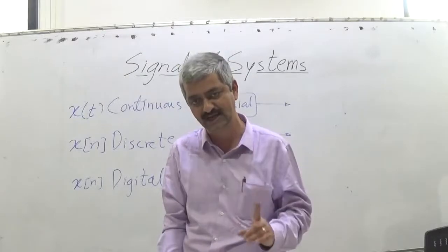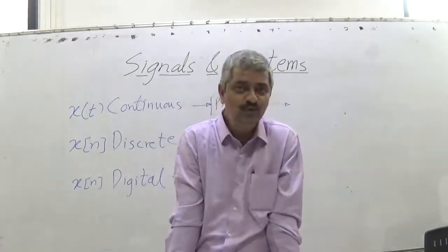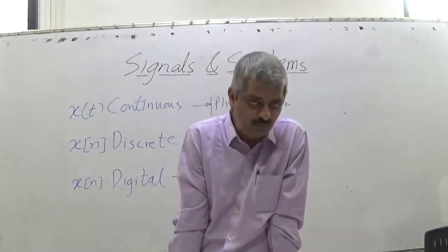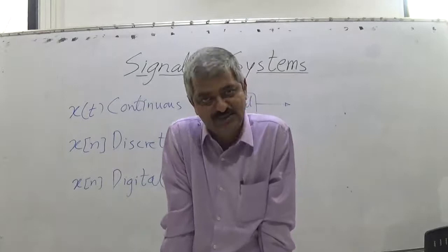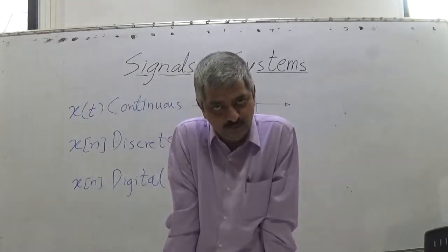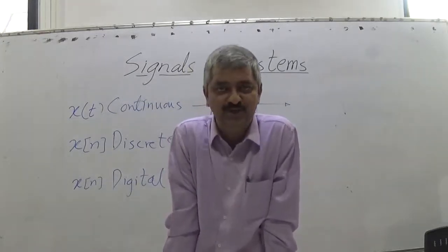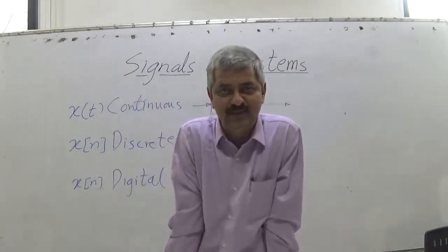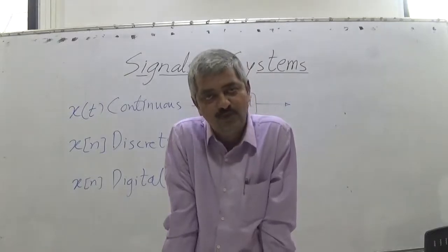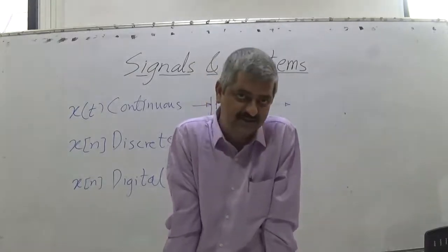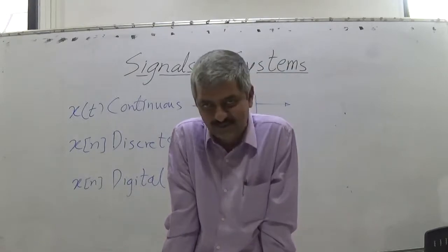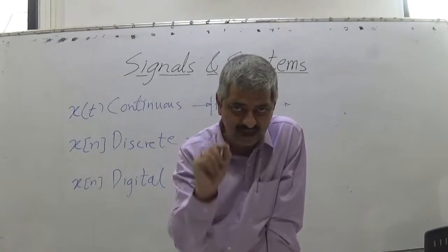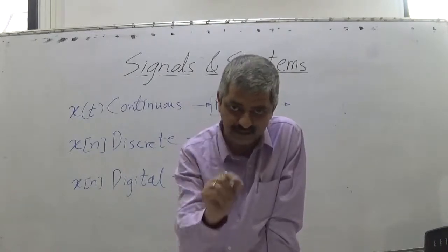So what you have to decide is, when you are having a finite number of digits, you have to define how much resolution you want and how much maximum size you want. If you want lesser resolution, for the same digits you can express a larger size. If you want finer resolution, the maximum size will be smaller. Then there can be a logarithmic scale also. Right now all those details are not so relevant. The theme is that when we digitize, the resolution is finite.